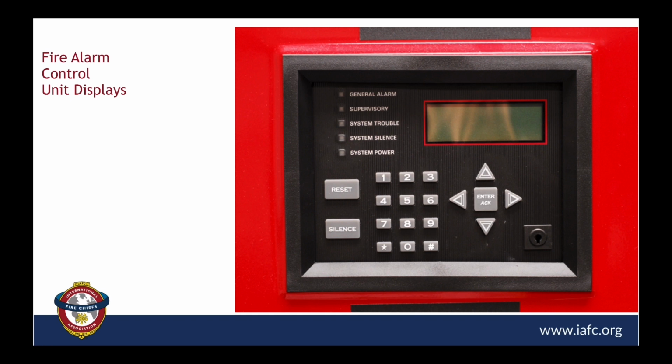The third light down, and so far these are going to be, by the way, lights you see on every panel, is the system trouble indicator. When that's on, that means that there's something within the overall system that's not normal. Generally, these systems are all fully electrically supervised and everything connected to them is supervised.